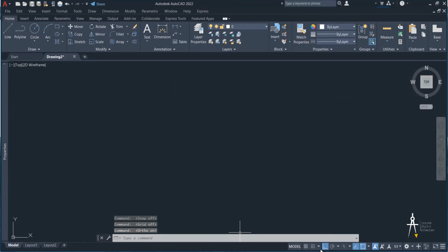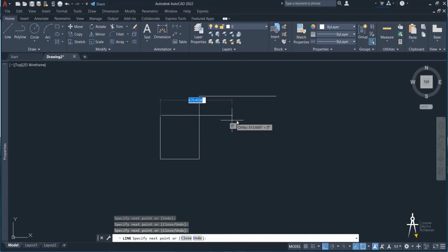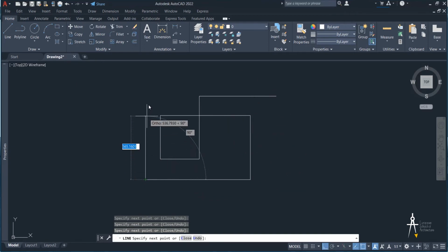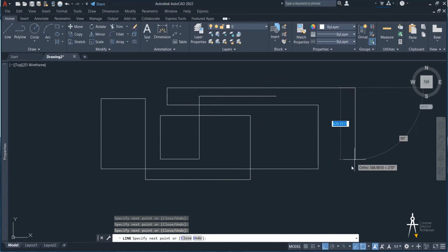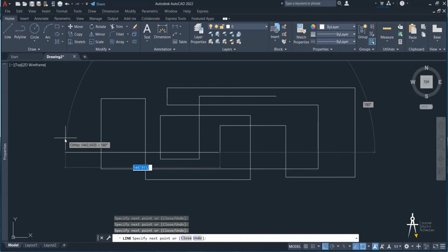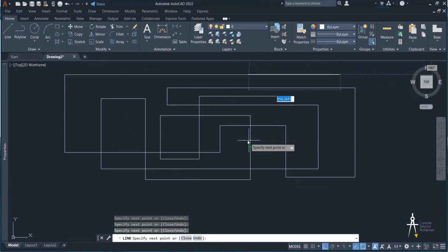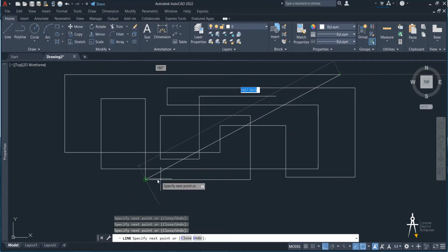This one's called Ortho Mode. If you click on it, you will see, I'm going to click the command line. I'm going to click on line, and I'm going to do lines, and it's only going to allow me to draw vertical and horizontal lines. So as you probably know, when we draw architecture, we are going to be drawing with orthogonal lines virtually all of the time. And if you're drawing very quickly and you don't want to do diagonal lines by mistake, it's a very useful tool.